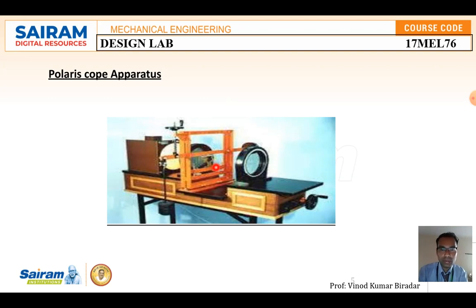Okay, so keep here, and at the right hand here we are going to substitute the load, or each time we are going to add one load here. For 1 kg of load you will observe, look here, your eyes close to this light. Here you are going to get the number of fringes on that photoelastic specimen.